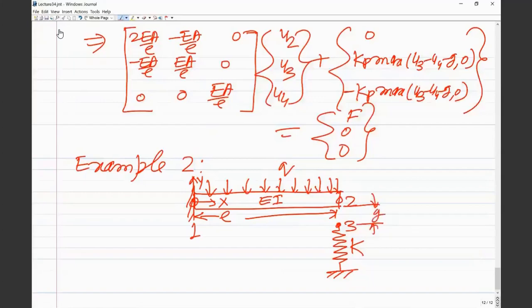So try to look at the solution of this problem using the same steps which we have done for the truss, the rod problem. First solve the problem in 2 steps, assuming that the gap is open, then identify the critical value of Q equal to Q star, below which the contact is open, and above which, when Q is greater than Q star, the contact between 2 and 3 is closed, and like that you solve the problem.